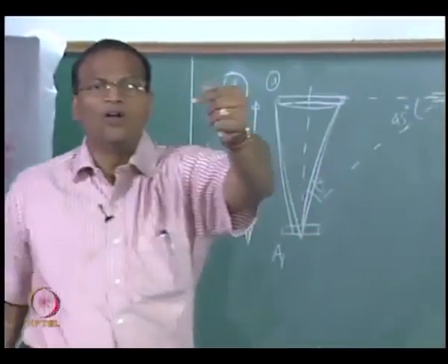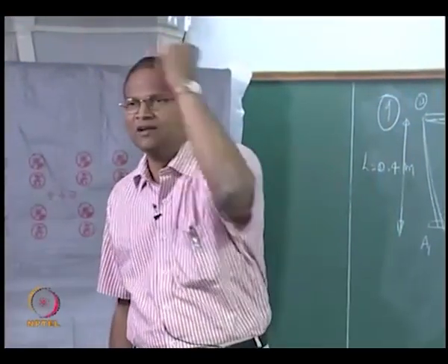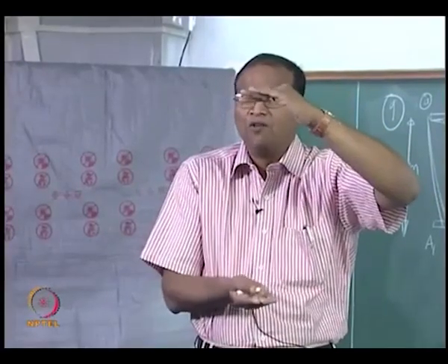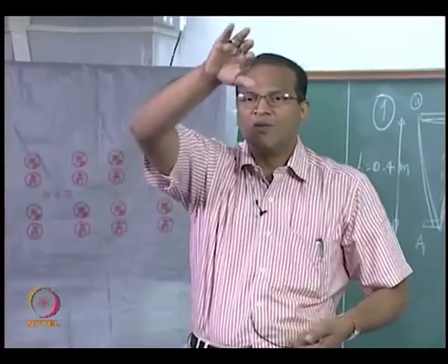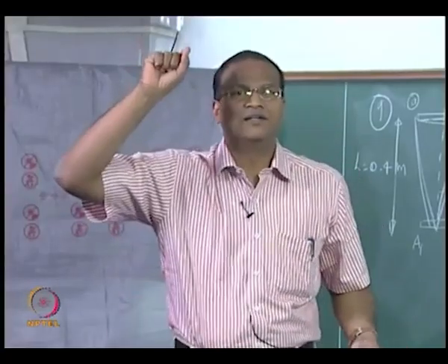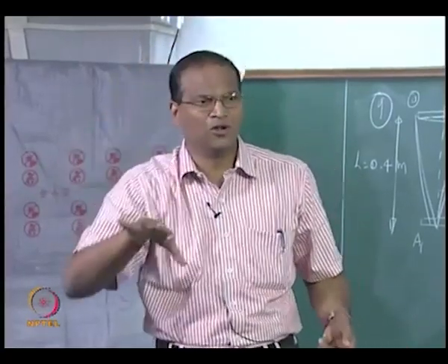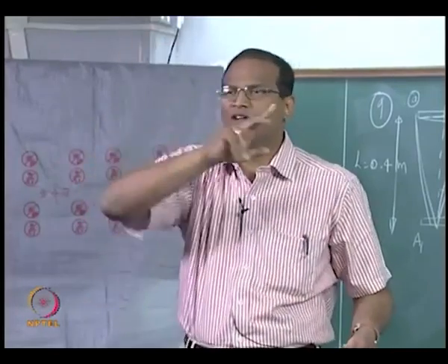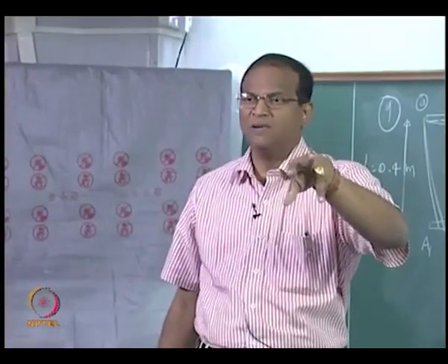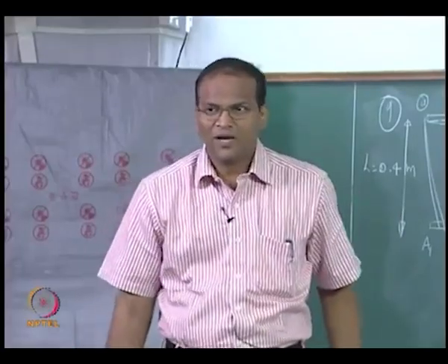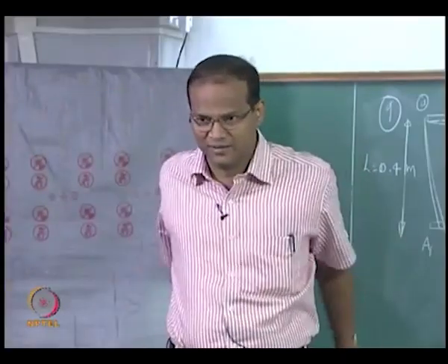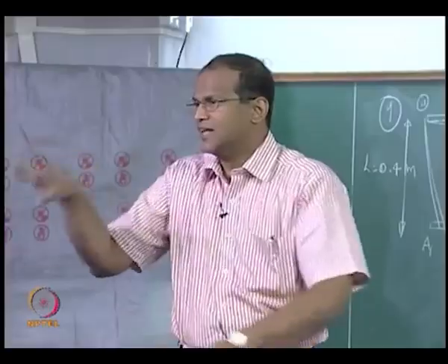Now the more difficult part is, this detector is now moved horizontally, so that cos 0 is no longer cos 0, it is cos of theta now, and this distance 0.4 meter is also changed, because now it is at an angle. Because the distance is also increased, expectedly the radiant power intercepted by A2 has to go down. If I have given a value greater than this, straight away you can say the problem itself is wrong. Now from 10 to the power of minus 6 it became 10 to the power of minus 7. That does not mean emissivity is exponentially going down, because other factors are not helping it receive more radiation, like the radius has increased and the angle has also changed from 0.